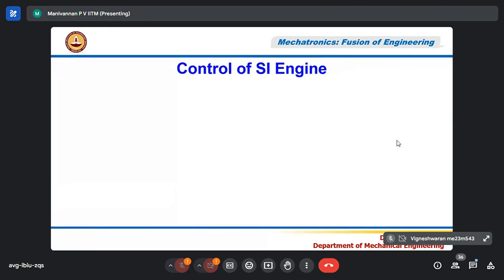Okay. So now, we know that air-fuel ratio control is the most important in this. Air-fuel ratio is nothing but mass of the air divided by mass of the fuel. Now we know that in a petrol engine, air-fuel ratio should be maintained somewhere from 8:1 to 22:1, and it may sometimes go to 24:1, slightly higher in the case of a GDI engine.